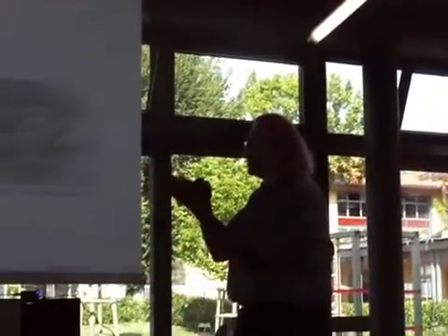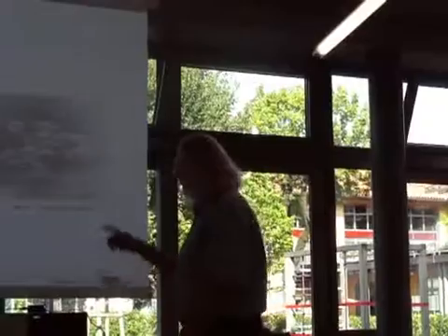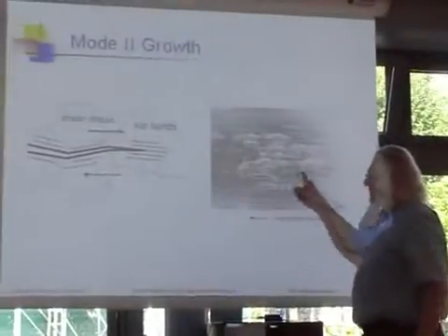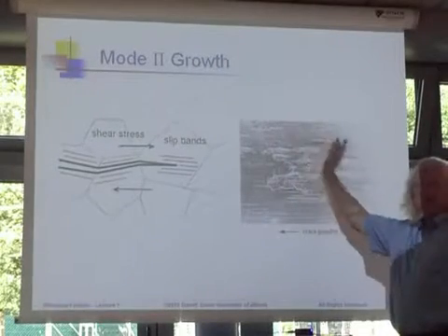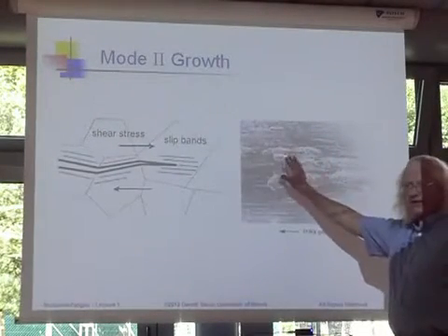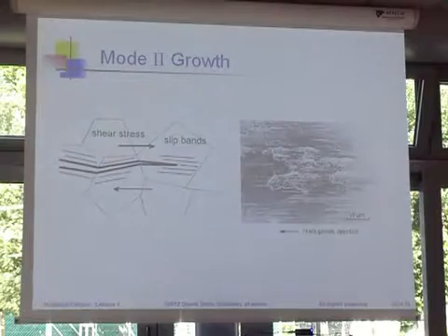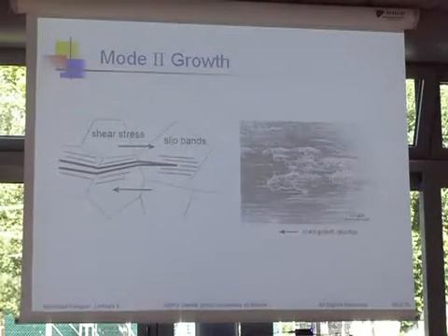That's the key, right? The key is we think about, I'm going to grow cracks, micro cracks or otherwise, and that process is going to happen in shear when they're small. But in the shear mode, there's just a lot of friction. A lot of friction, and you can see it in these pictures. You can just see the evidence of that. And that's an important, maybe the most important part of the driving.